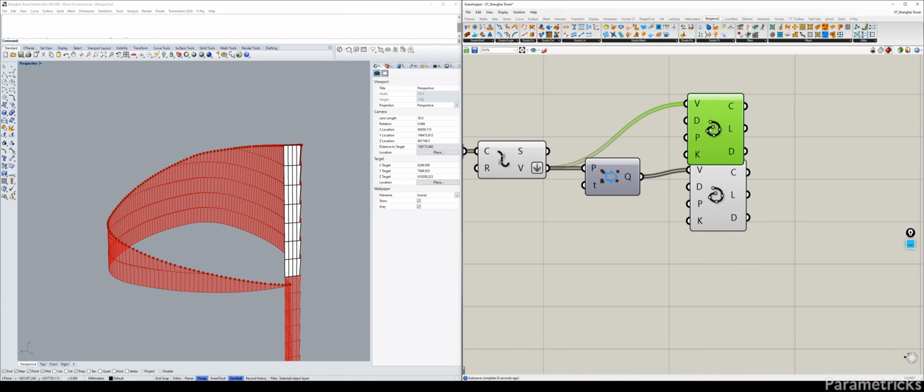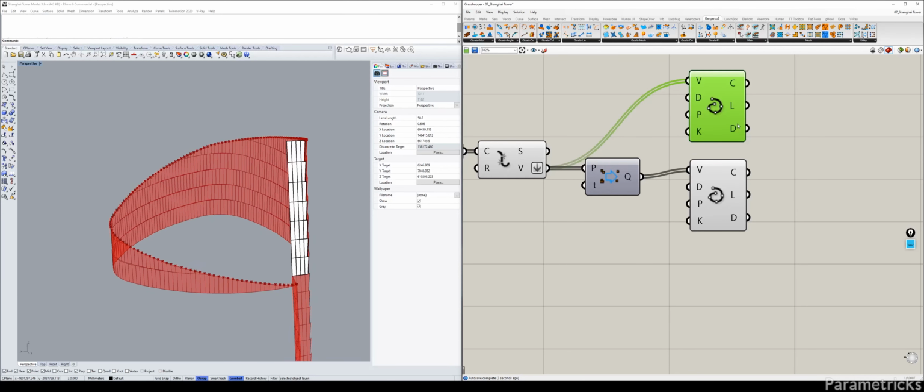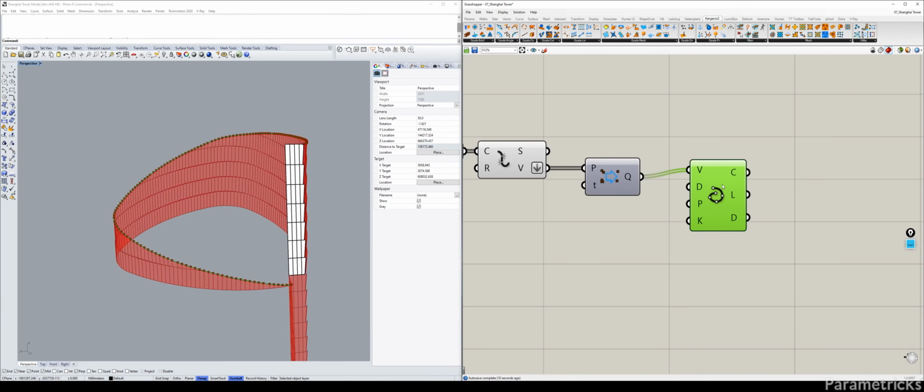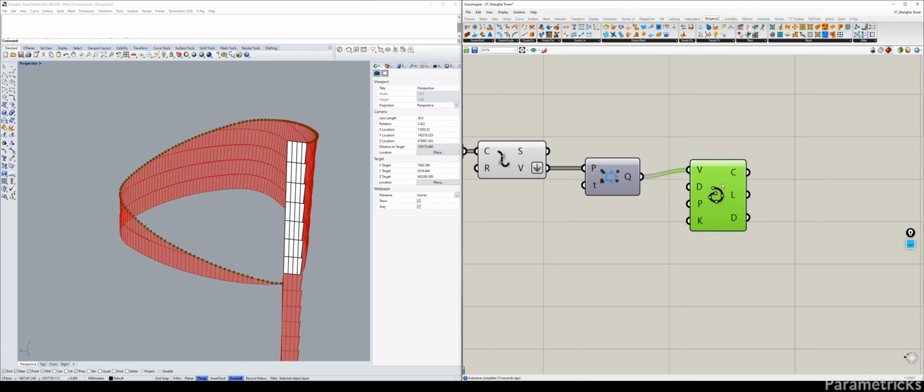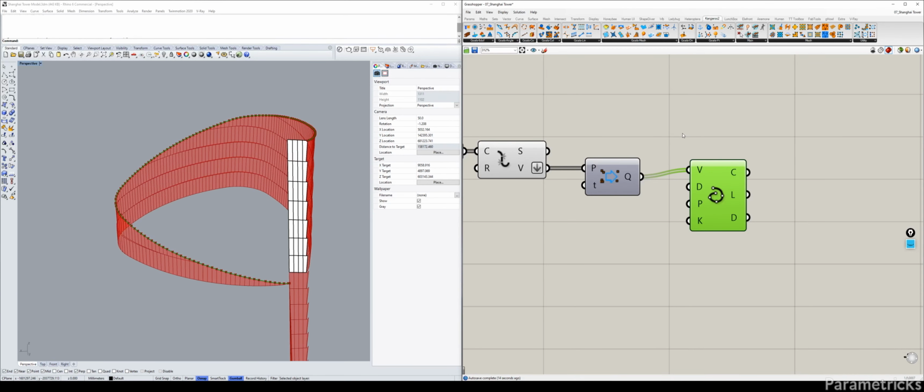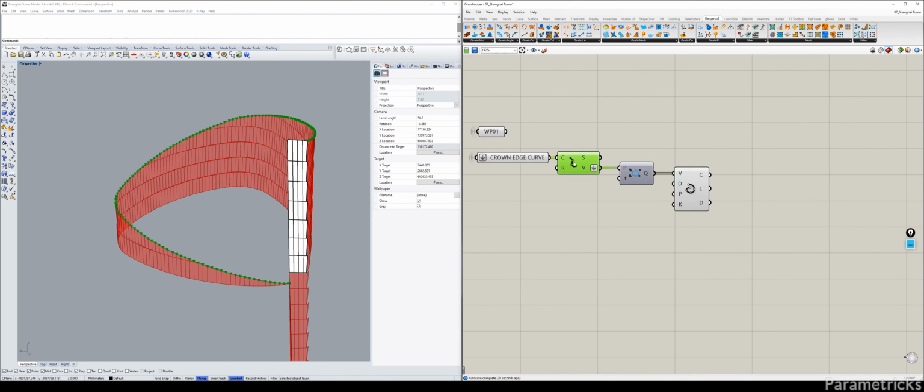And I can show you what you get if you don't remove the duplicates. Well, it just gives me a null because I think certain points are going to be connecting where you form a line with 0 length. So make sure that you remove the duplicate points. So I can actually now hide that and have a nice interpolated curve.